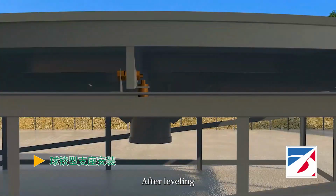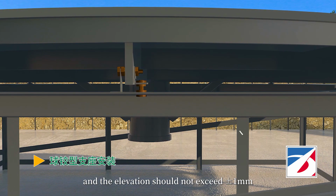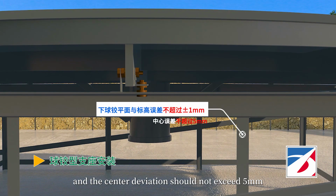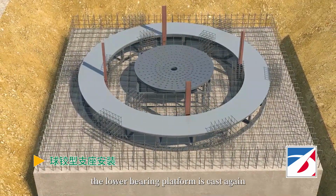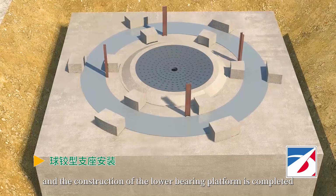After leveling, the deviation between the plane of the lower spherical hinge and the elevation should not exceed ±1 millimeter, and the center deviation should not exceed 5 millimeters. Then the reinforcement is bound. The lower bearing platform is cast again, and the construction of the lower bearing platform is completed.